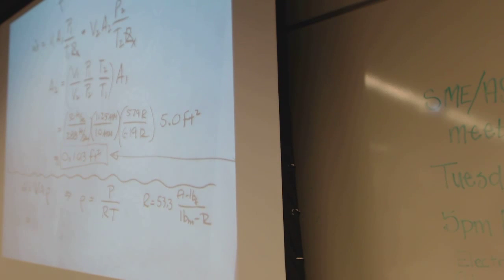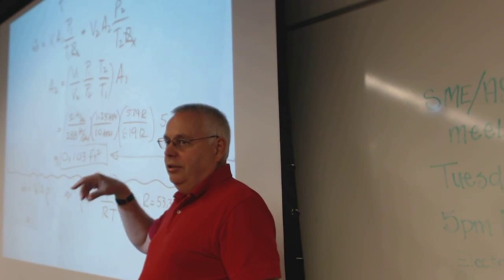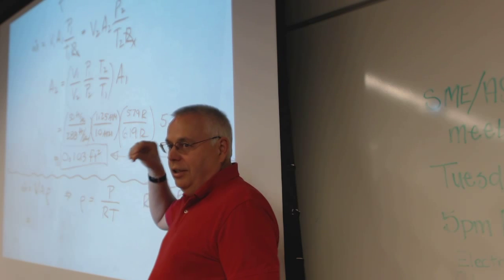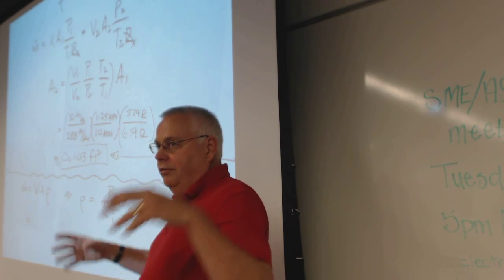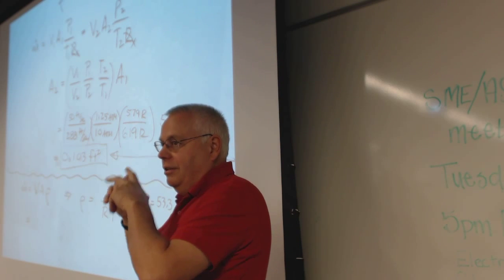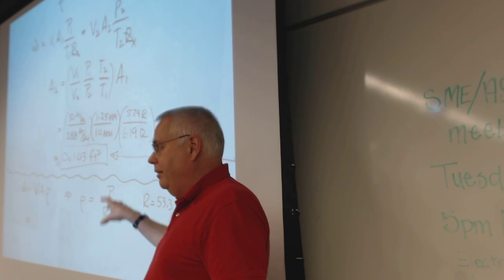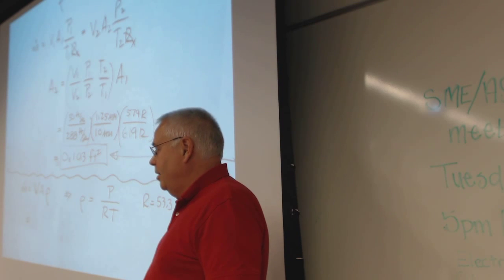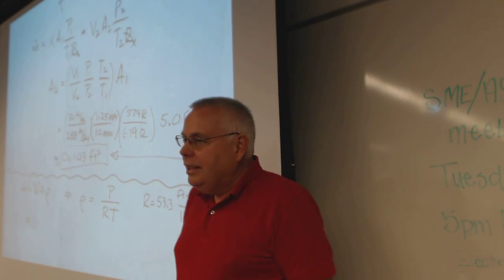In order for the outlet to go as fast as we said it was, in order for it to have that outlet temperature and that outlet pressure, that size nozzle is what we need. It's going down to 1/50th the size, but it went from 50 feet per second to 288 feet per second, which is pretty fast. So that's a nozzle thing.